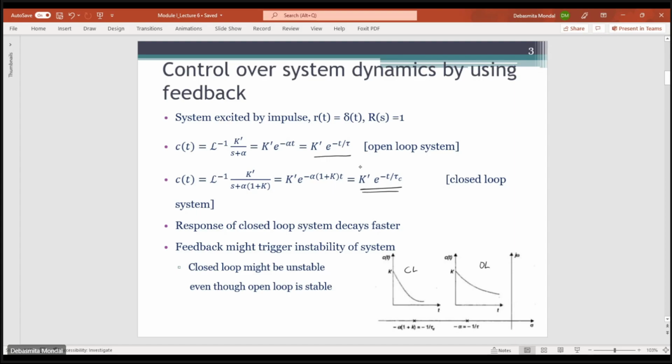To find that out, we first write the transfer function. Since we want to see the effect of the noise on the output, we consider that there is no input, so the only input to the system is N(s), and we make R(s) equal to 0.